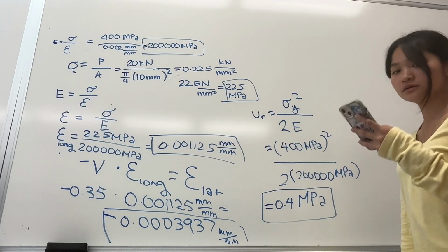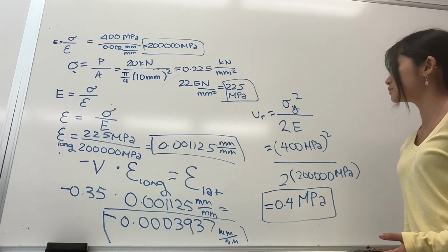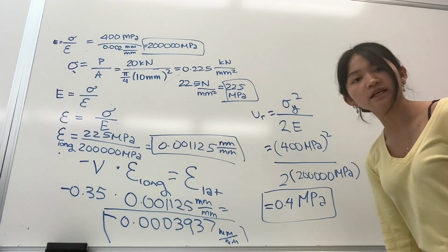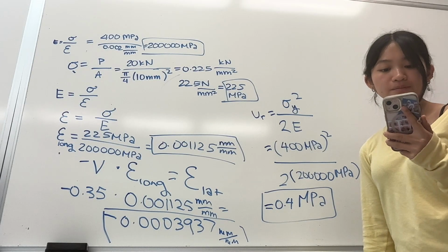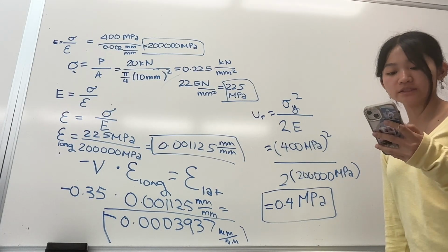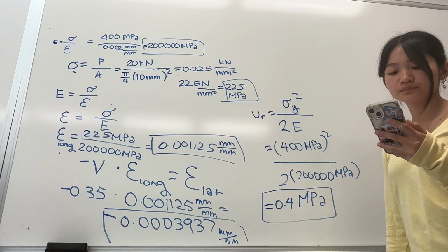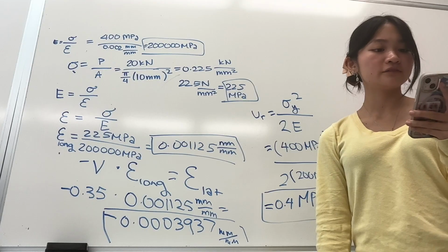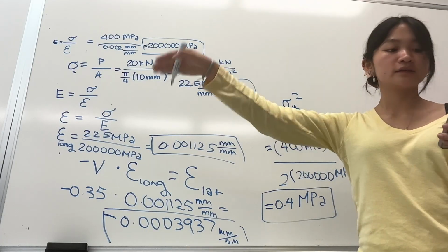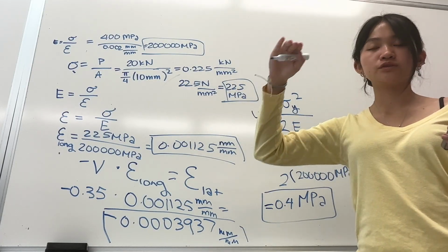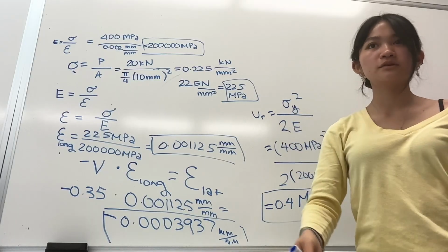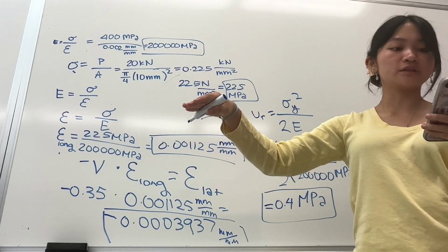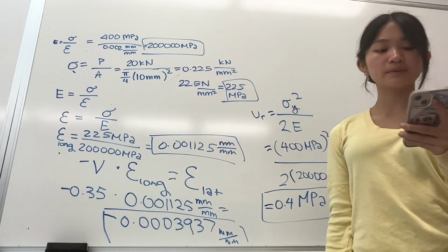And then we have one more part to the problem, which is finding our maximum tensile force that the material can resist. So we have our ultimate strength, which we showed in our graph, which is the very peak of our Y value, which is stress. So as we showed in the graph, that would be 500 megapascals.